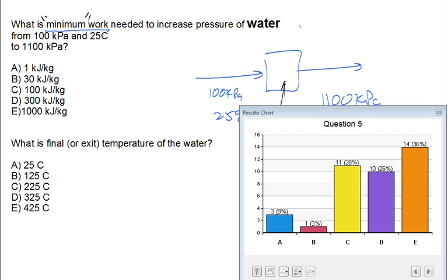And so the minimum work is the specific volume of the incompressible liquid that doesn't change between inlet and outlet. So V1 is equal to V2. And the dP is the change in the pressure. Well, this is a low blow, but I know the density of water, about 1,000 kilograms per meter cubed, but I can't remember the specific volume of water. 10 to the negative 3, 1 over 1,000. So it's 0.001 meters cubed per kilogram. Professor, I didn't have time to look that up. Some things you should just try to remember, right?